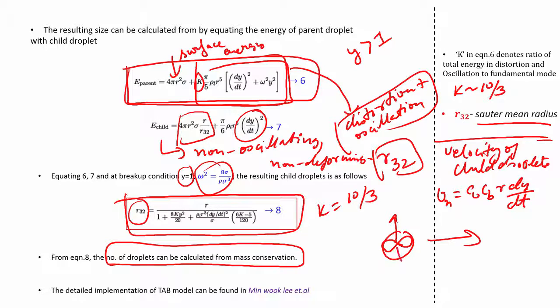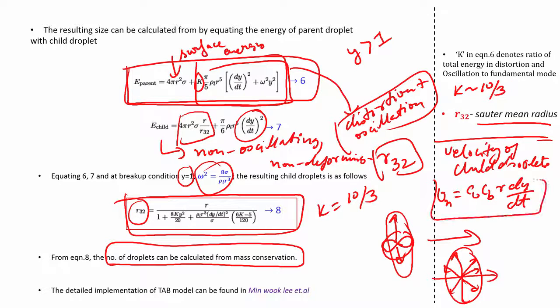As the droplet spits out, it spits out in those perpendicular directions. Now, it can happen in a plane anywhere around that perpendicular plane. So, if it is going like this, the daughter droplet can come anywhere in this plane, all of these are perpendicular. Velocity magnitude is given, the plane is given, but the exact direction is completely arbitrary. There is a certain randomness, because you can never predict exactly how it is happening. Okay. So, this gives you the velocity of the daughter droplet.